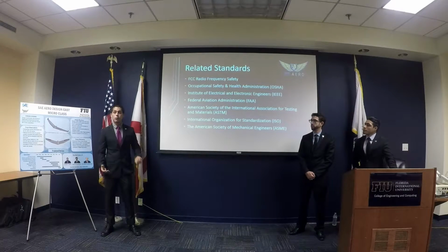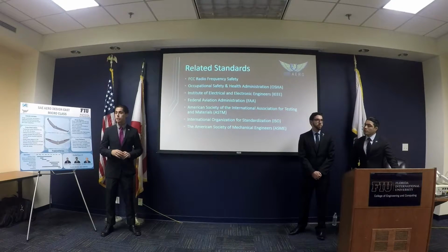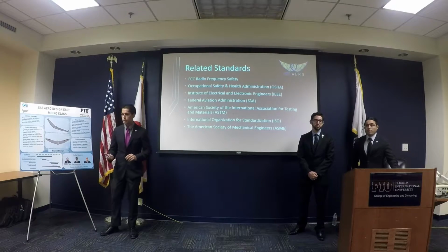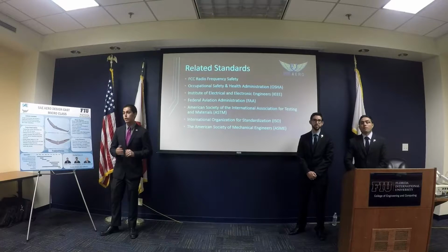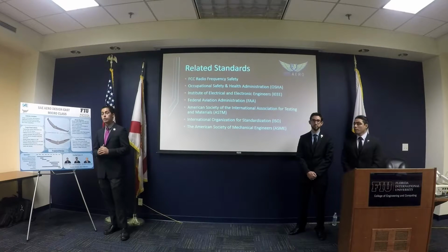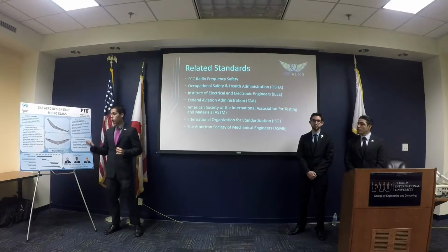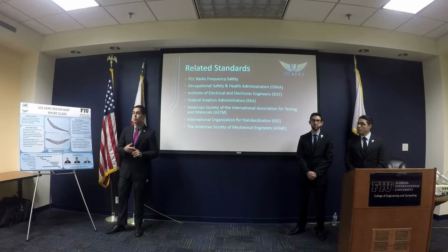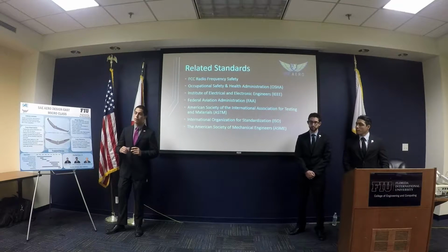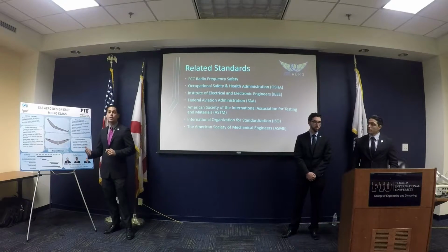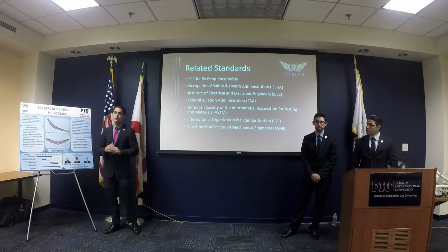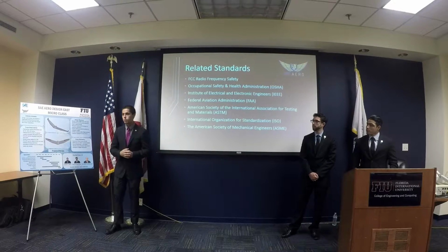All right, so some related standards. Although this competition does have some standards set by the organization SAE, two of the biggest standards we have to take a look at is the FCC radio safety requirement. We have to make sure the frequency we broadcast at controlling our remote control UAV does not interfere with emergency signals or any other broadcasts that are busy. Another really big standard we have to abide by is the FAA, the Federal Aviation Administration, requirement that if our UAV weighs over 5 pounds, we have to get it registered by them. This is a non-issue though. It's as simple as paying $5.